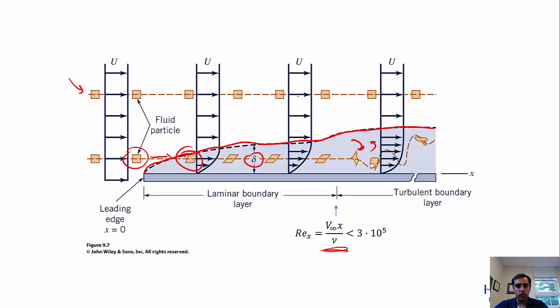All right. So the boundary layer has this velocity profile where we have the no slip condition at the wall. The further away from the plate I get, the faster and faster the flow becomes, until eventually, at the end of the boundary layer region, the velocity is the same as whatever it is in the free stream. And so you see that the velocity profile becomes flat, or a constant value. As the flow progresses downstream, since that height gets larger and larger, the actual profile itself is going to be changing accordingly.